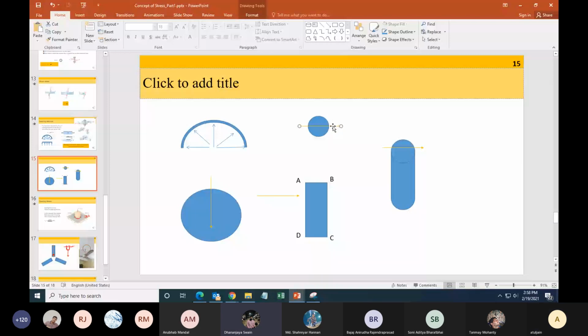No. That will not happen because the two forces that are there on the steel are not concurrent. It will be something like this. This will cause shear, not bearing. Bearing would happen if it would be this. But there is one plate on top of the other. So it will be like this.